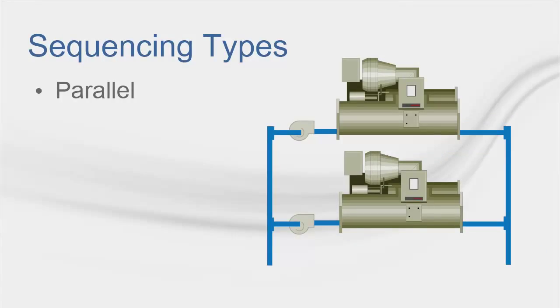Parallel sequencing indicates chillers piped in parallel. When this sequencing type is used, the first chiller listed will load first, and when the maximum capacity is reached for that chiller, the load is then split proportionally in relation to the design capacity of that chiller and the next one in sequence. This scenario uses a dedicated pump for each chiller to circulate water throughout the system. This sequencing type can be used with both variable speed pumping, variable primary flow for instance, or constant volume pumping schemes.